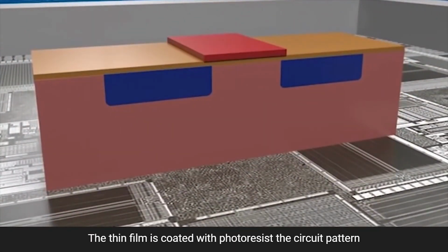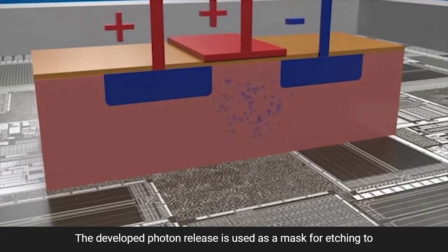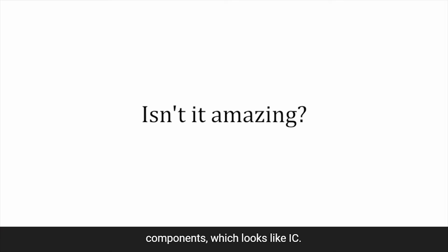The thin film is coated with photoresist. The circuit pattern of the photomask, that is reticle, is then projected on the photoresist using photolithography technology. The developed photoresist is used as a mask for etching to process the thin film into the shape of wiring and other components which look like an IC.